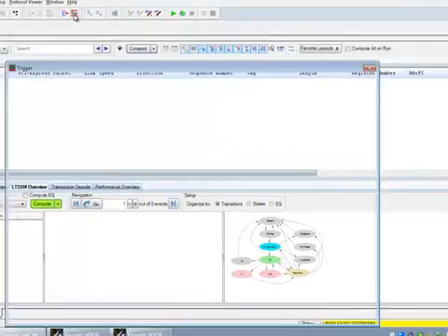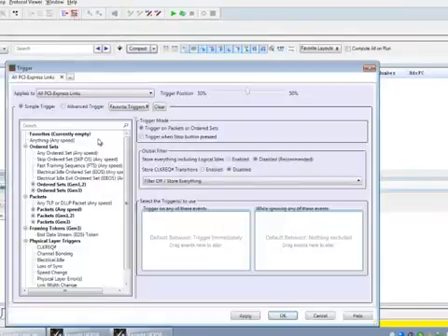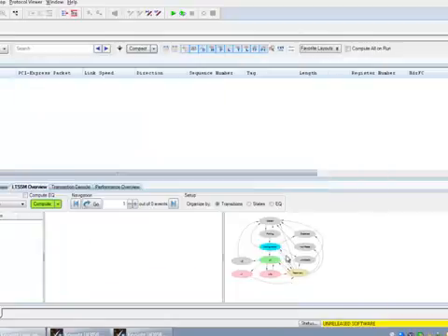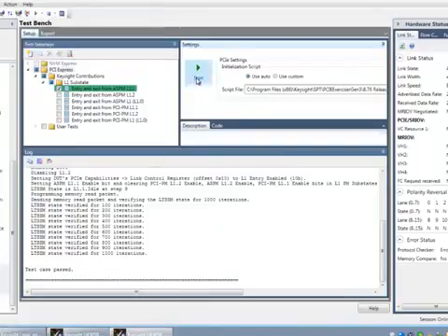My trigger menu is what do I want to capture. I have my filter and trigger capabilities here. Right now the filter is off, it's storing everything, but I want to capture these clock requests. Normally we'll ignore those, but if we want to analyze those, we turn on that sideband acquisition, enabled. Okay, click OK, and we're set to capture. So now let me start my test again. I'll run that test again.